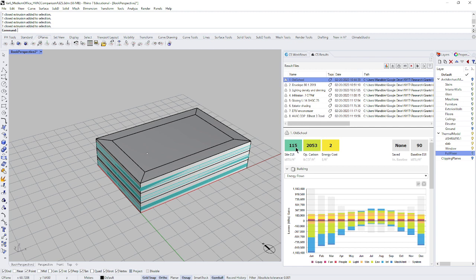So that's the amount of energy that we're using on site per square foot. So it's kBTUs per square foot per year. That allows us to compare apples to apples because larger buildings are naturally more energy efficient because they have less surface area per volume, and the surface area of the envelope is what you lose your heat through, or you gain your heat through.